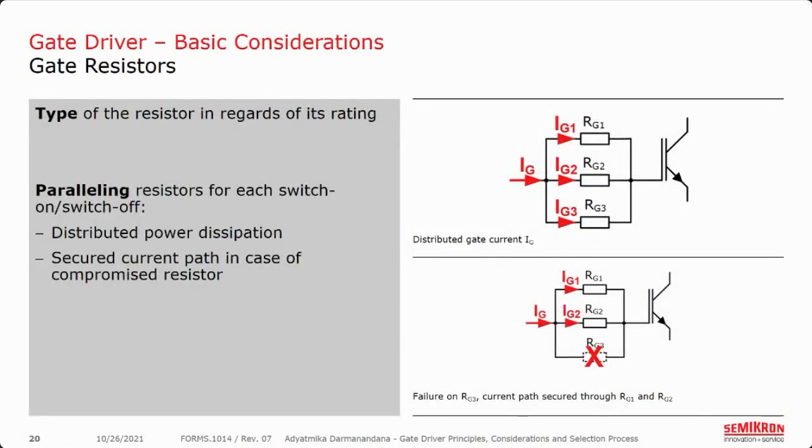With information about the power dissipation and peak current, the type of the resistor needs to be considered. Depending on the application, use of a MELF type to secure operation with high dissipation may be needed. Another tip is to apply the gate resistance as a parallel circuit of some resistors. An opening of the gate circuit can cause the IGBT to remain on, and this can be very dangerous for the system in general.